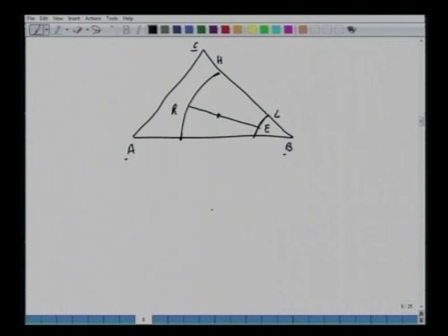So again, if you choose M, mark this coordinate as M, and say that you have reached equilibrium, the raffinate will contain a certain mole fraction, say XR of C. The extract will contain a certain weight fraction of C again. If you choose any other mole fractions here, again allow them to settle, there will be a tie line, and they need not be parallel. Again you can apply the mixing rule to obtain how much is the amount of R and how much is the amount of extract.